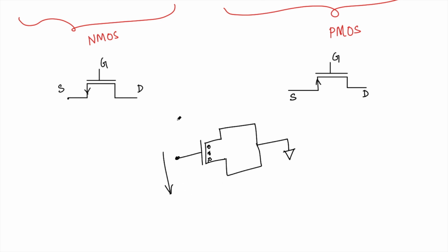Because these two are in reverse operation, one has to go to the positive side and the other has to go to the negative side. Because of this property, NMOS and PMOS are called complementary MOSFETs. They have a complementary nature: for one we need to increase, for the other we need to decrease. That's why it's called CMOS technology. And especially it is good in digital circuits, when one is turned on by applying a high voltage, whereas if I apply a high voltage in case of the PMOS, it will never be turned on, it is off, and the reverse happens for the NMOS.